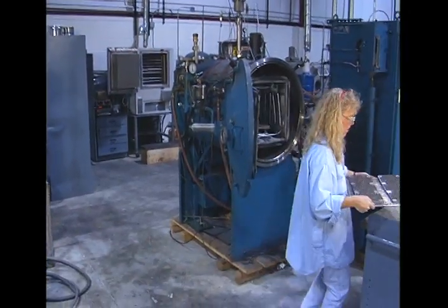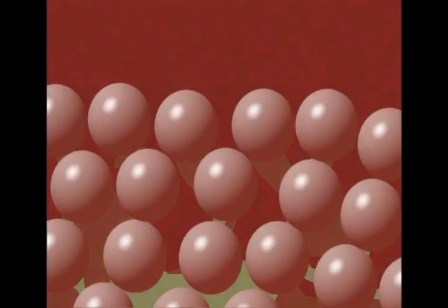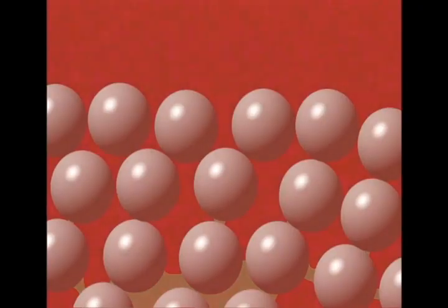Sintering follows in a two-stage furnace. In the first stage, the remaining binder is removed at an elevated temperature. In the second stage, the part is sintered. During sintering, the part shrinks, removing almost all of the porosity.